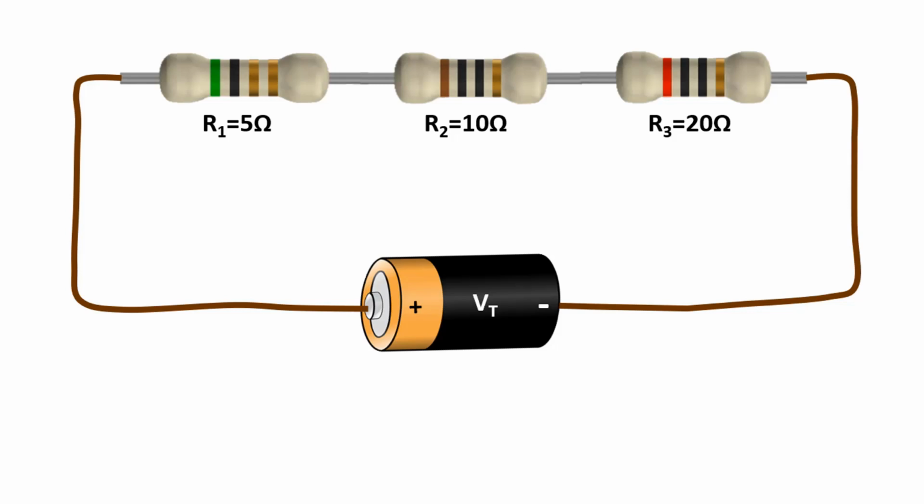But in circuits where we can't see the direction clearly, don't worry if I can't find the direction of the current. We can estimate a direction. If the current value we find is positive, the direction we determined is correct. If the current value we find is negative, it is in the opposite direction of the direction we have determined.